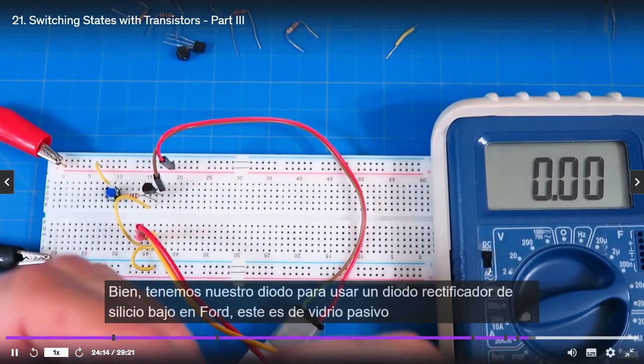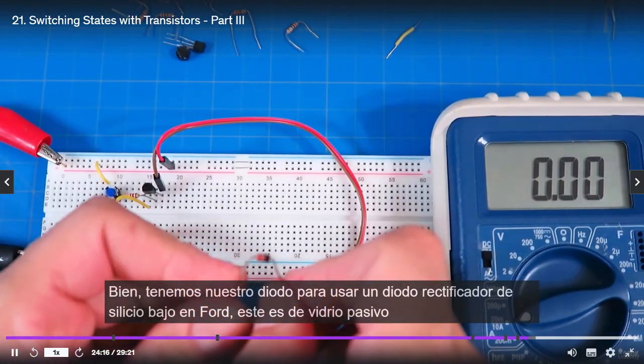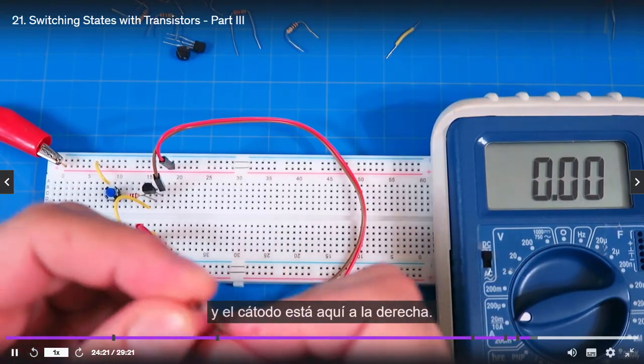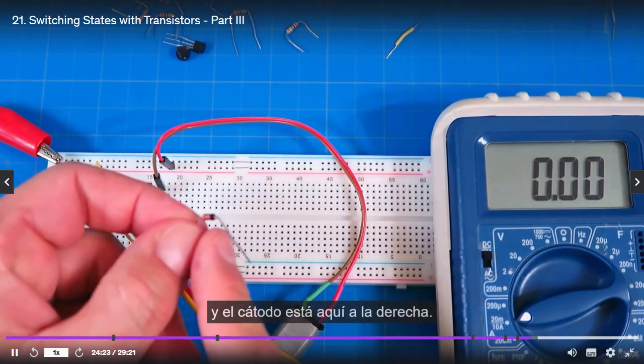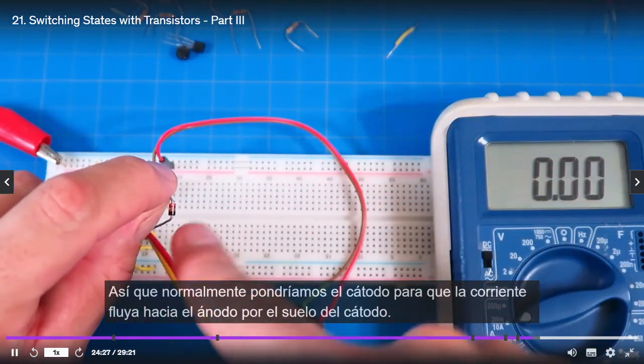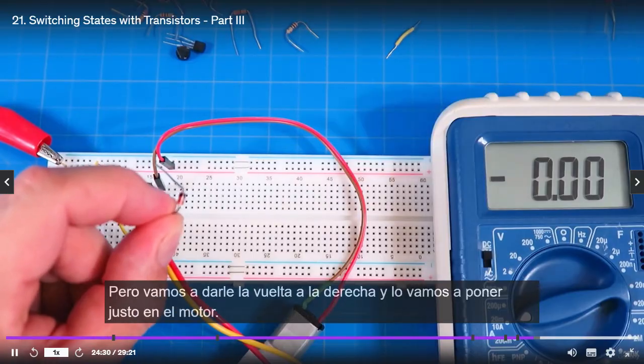Okay, so we've got our diode. We're going to use a 4001 silicon rectifier diode. This one's glass passivated, and the cathode is over here on the right. Normally current would flow into the anode and down the cathode to ground, but we're going to flip it around.